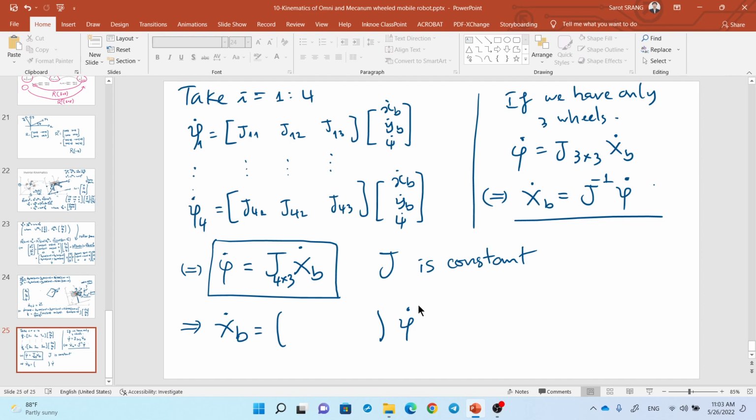I mean input like velocity of the wheel, and then velocity of the robot on x, on y, and rotation. So it's like you have three unknowns, three equations. So three wheels is okay to determine velocity x, y, and rotation. But if you have another wheel, if the fourth wheel rotates not properly, it just fights with the others. You got the point?